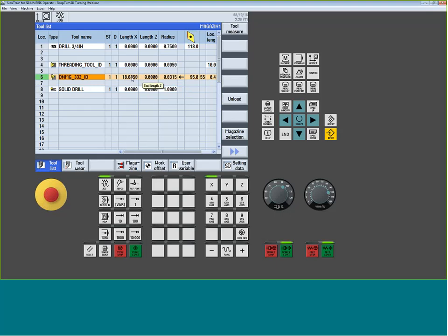Or do I want to set things up from some kind of a gauge line. If I have modular tooling, it's much more proficient, obviously, to set things up from a gauge line. Then in that case, I'd have these small lengths, and then I have to find where the physical part is by using my work coordinate system.